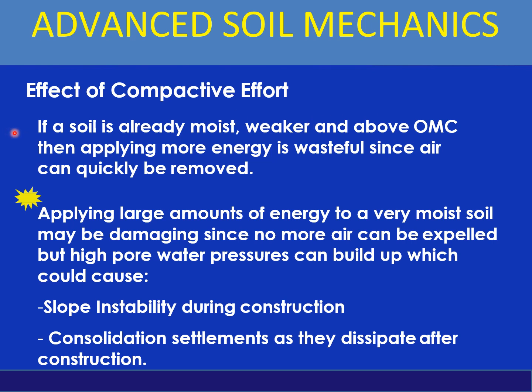If a soil is already moist, weaker, and above OMC, then applying more energy is wasteful, since air can quickly be removed. This point is very important: applying large amounts of energy to a very moist soil may be damaging, since no more air can be expelled, but high pore water pressure can build up, that would cause slope instability during construction, and consolidation settlements as they dissipate after construction. So this point is very, very important.